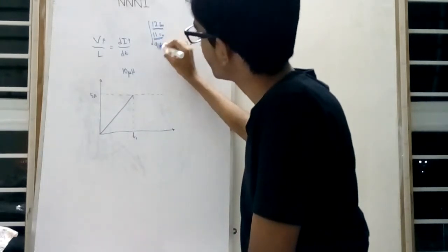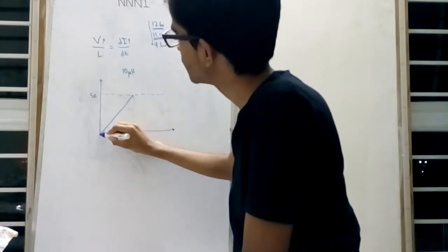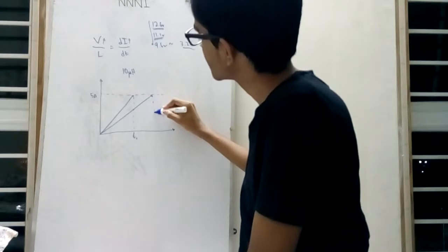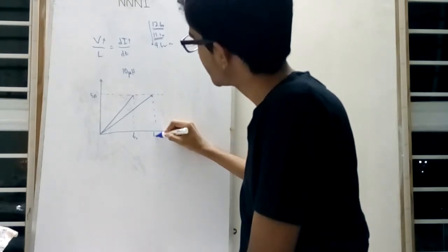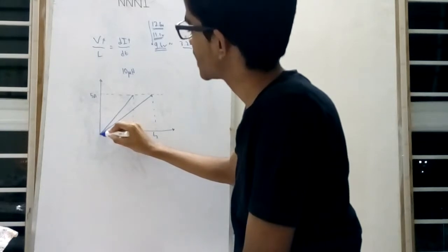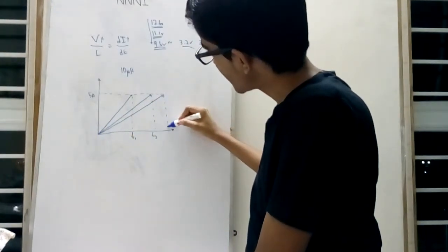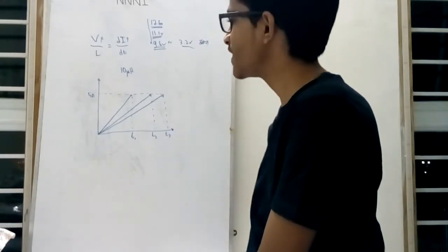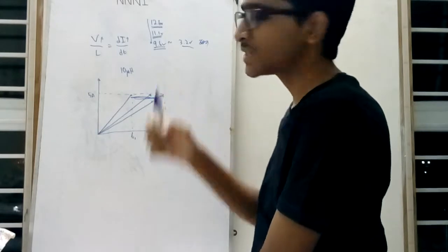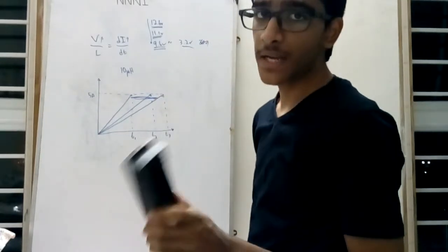And now at 11.1 volts, the current rise is going to be a bit slower, and it reaches 5 amps at T2. And at fully drained, the current rise is even slower than that, and to reach 5 amps it takes time T3. So you can see the big difference in the time depending on the state of your battery, and now that creates problems.